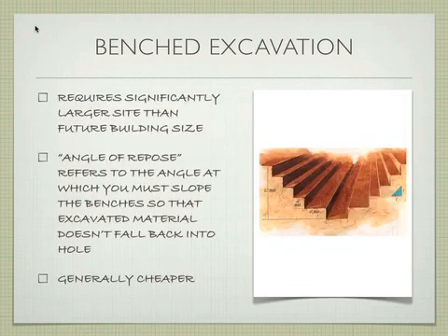The thing about a benched excavation is it requires a lot more space to do it, right? So you can't just dig, okay, I want my building to go here, I'm going to dig just the footprint of the building, okay? If you need to do a benched excavation, you need a whole bunch more site to dig so that you can eventually put your building in the middle of this. Okay, it should make some intuitive sense.